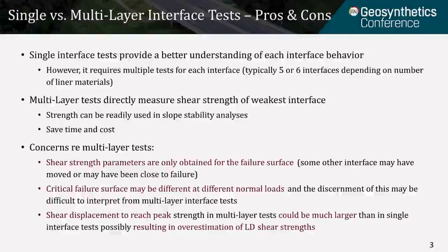Shear displacement to reach peak strength in multi-layer tests could be much larger than in single interface tests, shortening the post-peak displacement and thereby possibly resulting in overestimation of large displacement shear strengths. I will mainly focus on addressing these concerns in this presentation.